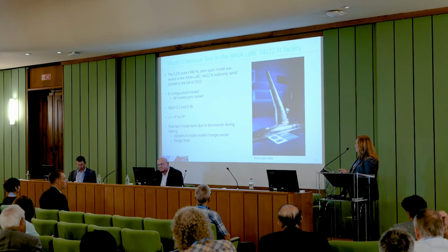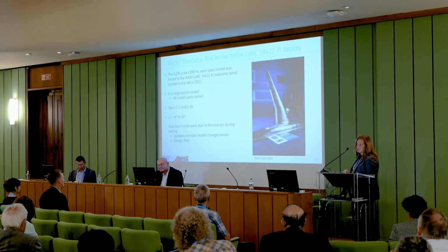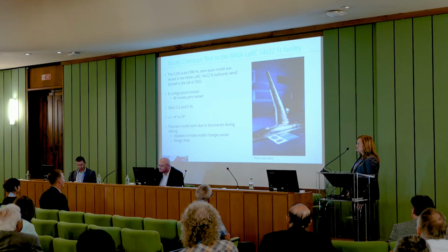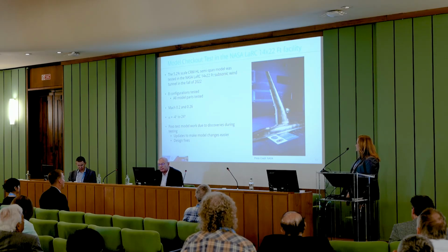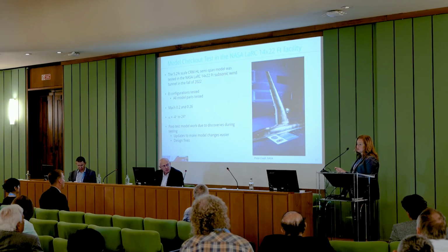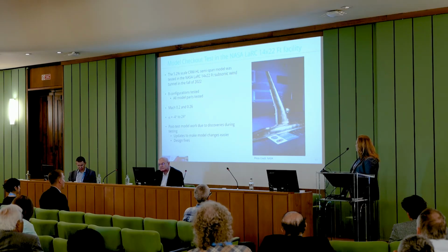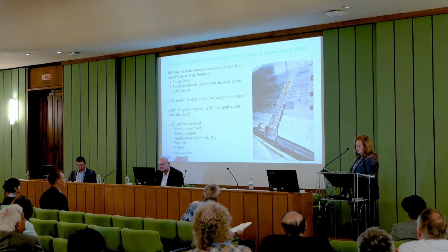We tested at the landing and the takeoff Mach numbers of 0.2 and 0.26. We ran at angles of attack from -4 up to 24 degrees. And because of this test, we did find several, I don't want to call them issues, but several things with the model that we could go ahead and update or fix. There were some model changes that were really, really difficult. They looked good on paper, but whenever the technicians actually tried to do the model change, it was a lot more difficult. So we were able to go ahead and make those changes. And that was before we sent the model over to the low-speed wind tunnel at Braunschweig.